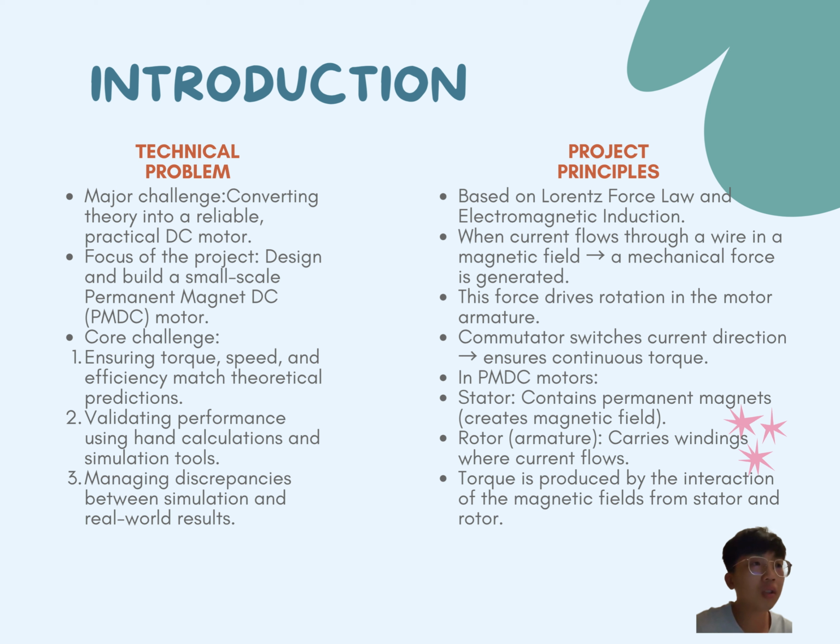When the electric current flows through the wire inside the motor on the rotor, the wire is surrounded by the magnetic field from the stator permanent magnet. So it will create a pushing force that makes the rotor spin. A commutator constantly reverses the direction of the electricity in the wire as the rotor turns. So it will push strong and constant because of the inertia.